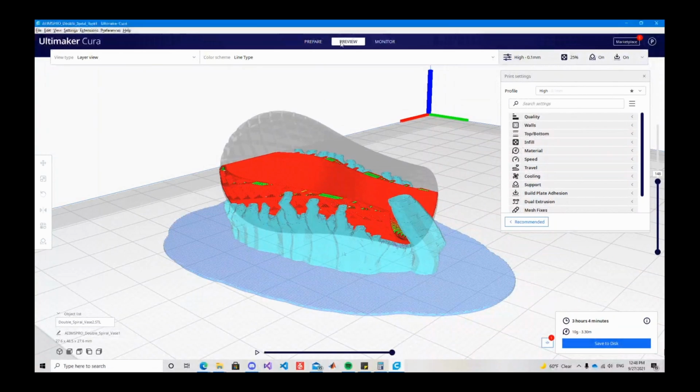The thing I would recommend is just buying filament. Whatever you want to print, buy tester filament, and try to figure out your settings and your environment, because that's another big thing. If your printer is an open printer, make sure you keep the temperature in your room, or wherever your 3D printer is, constant, because otherwise, that's an issue I had.